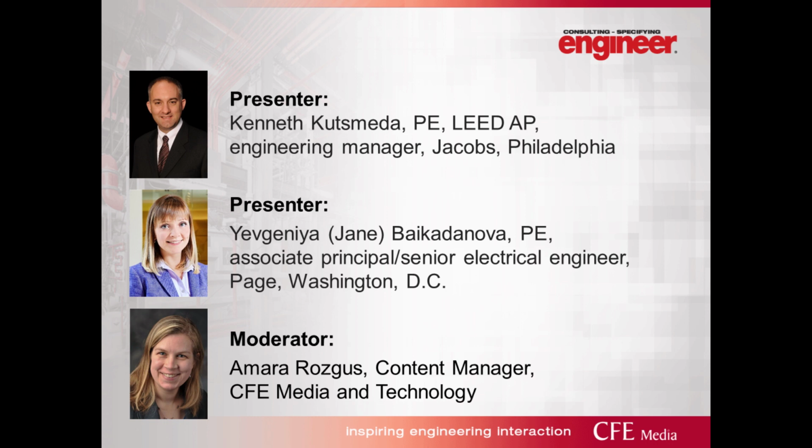For IFC 2015, it's only signage, seismic requirements, and smoke detection. For NFPA 855, or IFC 2018, which reflects the NFPA 855 requirements, there are additional requirements such as explosion control, size and separation, fire suppression, and thermal runaway. The big ones to look out for: the energy storage systems should be comprised of groups with a maximum stored energy of 50 kWh. So each cabinet should not be more than 50 kWh.